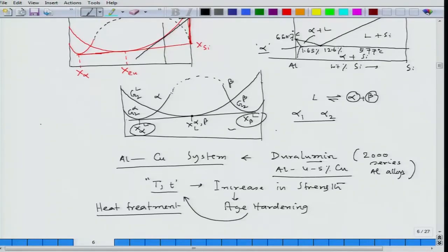Now we are talking about room temperature. Since room temperature diffusion is sluggish, if we put it at a little higher temperature, let us say around 170 degrees Celsius, this hardening process becomes quicker. Though the overall hardness would be lower, the process becomes quicker, which is of great advantage, because industry does not allow a very long time; a long operation means the cost would increase.